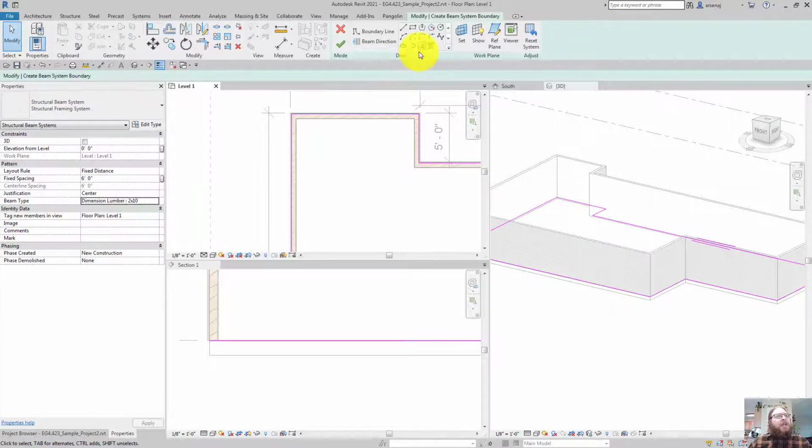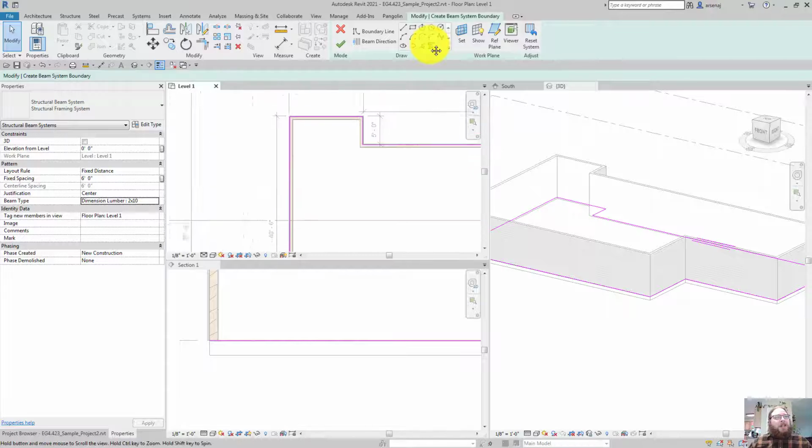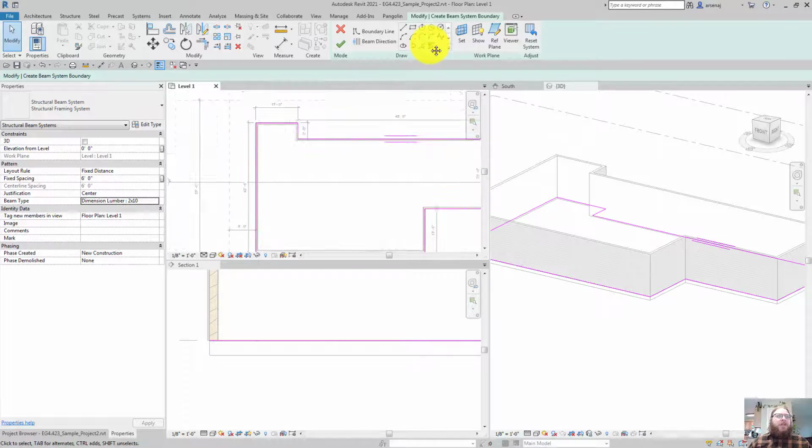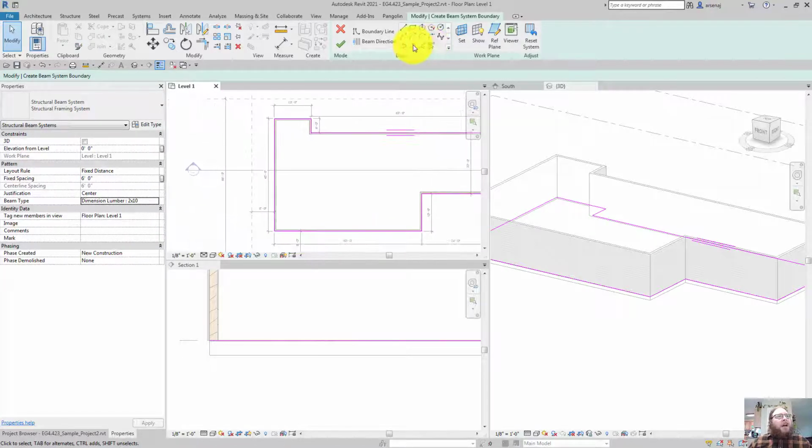And there's several ways to do this. Looking in here, again, like the floor generation, there's lots of different ways to draw it. Here it says you can pick supports, so add sketch lines based on existing structural walls and beams. Select structural walls and beams to define the sketch lines. Sketch lines will be placed at the center of the selected item. So that would be if you wanted to use any structural that we've already put in here.